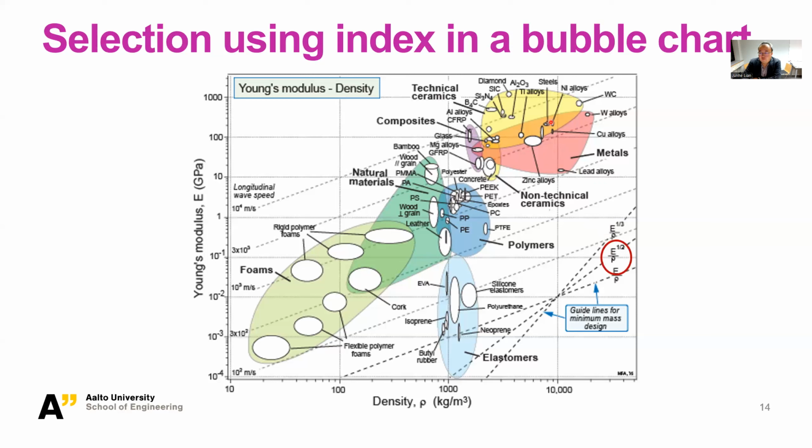And you might get a question related to this point. If we recall the airplane, when we talk about the spar, many of them are made of composite materials, and aluminum alloys could also be applied, but we never see steels applied in airplane components.